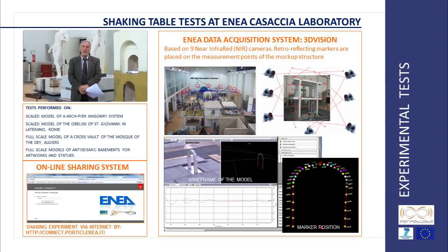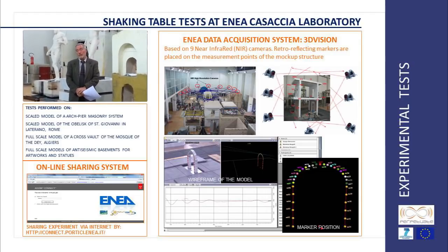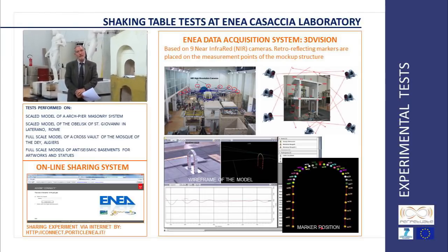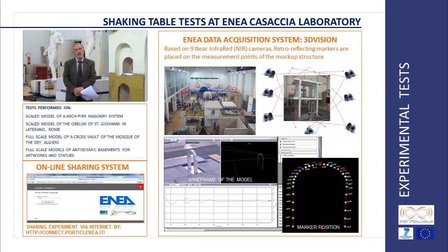It was also possible, in this way, to validate the numerical models, because the markers were positioned at the nodal points of the finite element model of the structures.